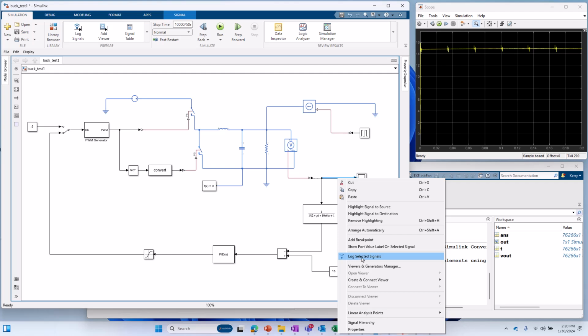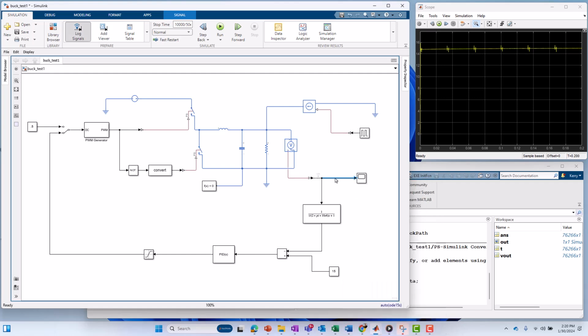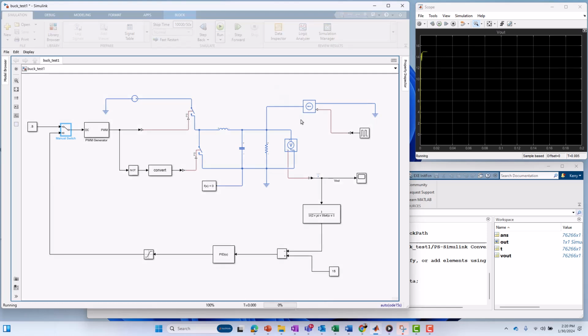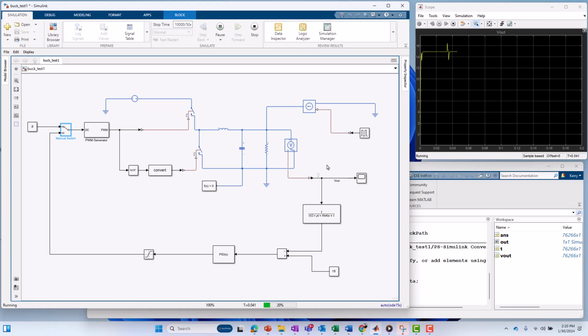One easy way to do that is to log the data at the node of interest, let's say the V out. And of course, we could also just rename our nodes as a form of description, annotation. We could just name it accordingly. I'm going to run it again. First of all, I'll do the open loop simulation first. This means log the signal, that little Wi-Fi like symbol. Let's go ahead and log it. Take a few more seconds to run.